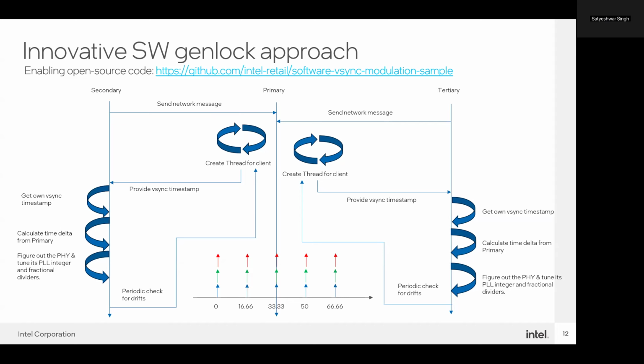Yeah, so to add on to what Ben was saying, it depends upon the resolution of your screen. If you have, let's say, 1920 by 1080, then each row is 15.4 microseconds. So if you have 1 to 2 rows, then it's essentially 15 to 30 odd microseconds that you want to synchronize to.